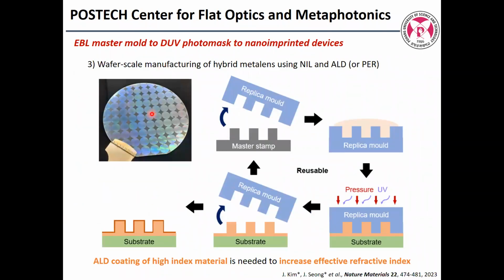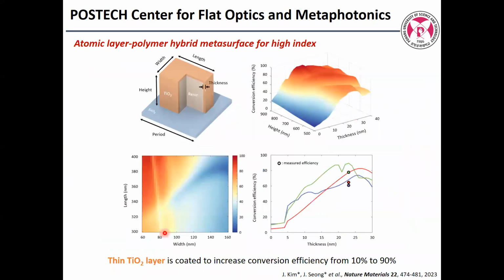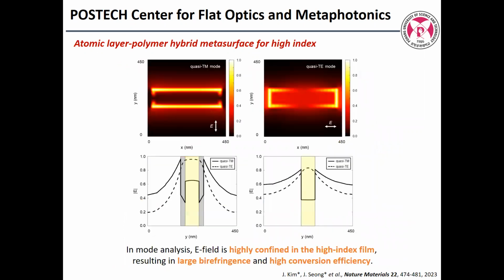So what we did: we do resin coating and printing, and a thin coat of 20 nanometer low temperature ALD. The 20 nanometer TiO2 will effectively make the entire medium act as TiO2. So this is the scheme: resin, thin TiO2, but the effective property of the entire structure acts like regular ALD TiO2. So we don't need 1 micrometer thick ALD; rather we use just the printing and 20 nanometer ALD coating.